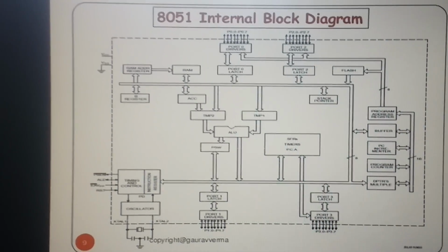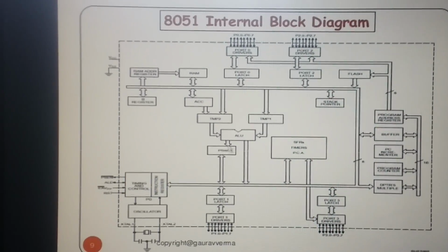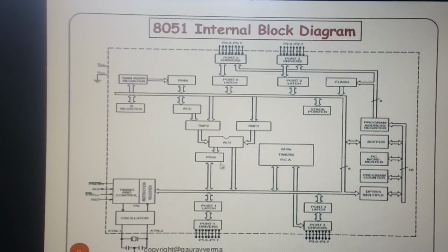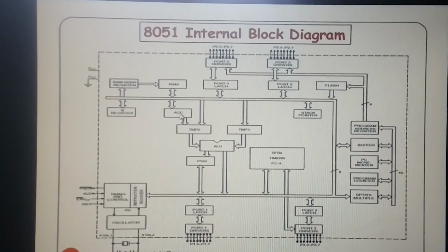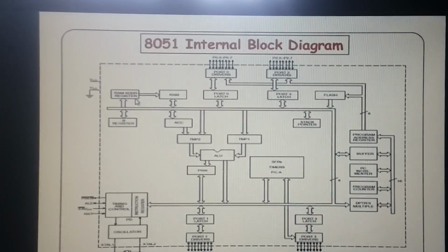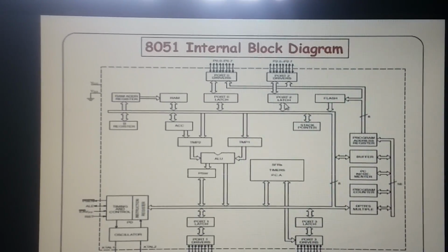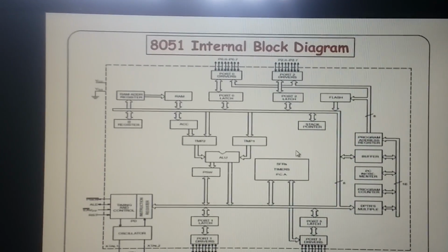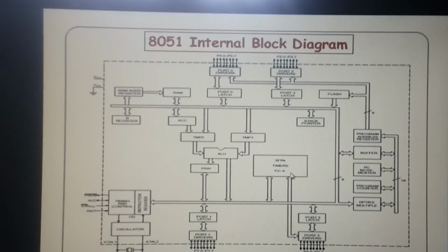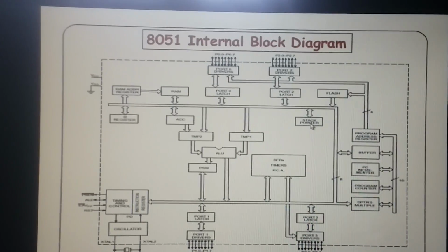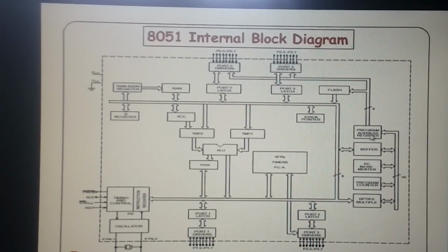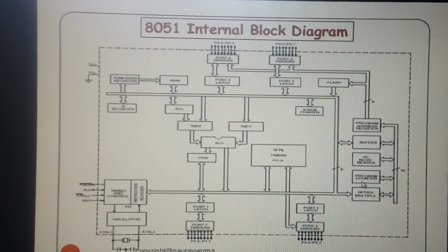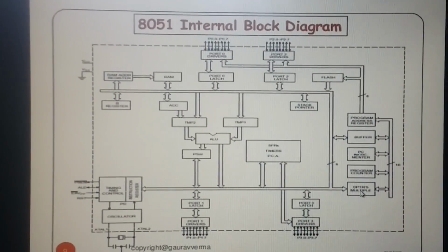Here we have the program status word, which is used to indicate the status of the microcontroller. The operation status is held in the 8-bit PSW, and we have the accumulator register, B register, RAM address register, RAM and 4 ports, port 0, port 1, port 2 and port 3, available along with the driver circuits. Moreover, we have a timer circuit here, and the stack pointer, flash memory, program address incrementer, buffer, PC incrementer, program counter and DPTR.